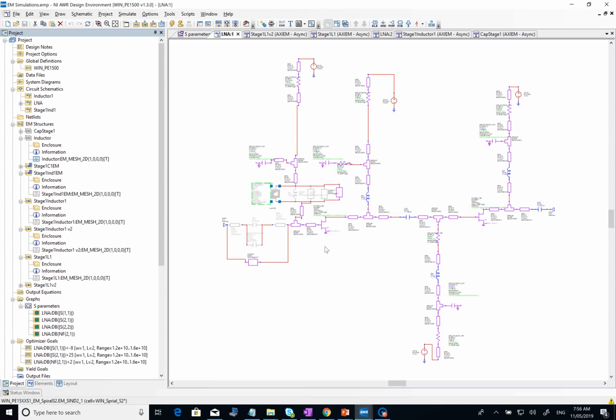Because when you go to review 4, you have to do the layout, and when you do the layout, you might have to re-EM it, which means review 4 is where I expect you to meet all the specs, or whatever specs you can meet in review 4. So in review 3, the main idea is to do the EMs and then arrange the components inside the frame and include the RF pads in the layout. Even if you don't show the layout in review 3, that's fine, but if a student chooses to show the layout, that's actually better, because that gives me an idea that you are considering the EM and the layout interchangeably.